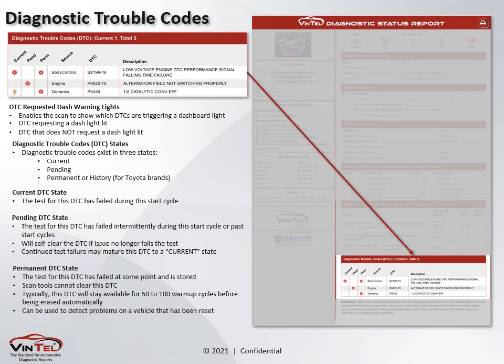So why use the diagnostic trouble codes? It's a great question. You already know in plain English terms simply what parts have to be replaced as well as what the labor is. When you get to this level though, you're typically trying to understand why these DTCs are happening and when they're occurring. So you're looking at states. Is it a current? Is it pending? Is it something I have to worry about maturing as they leave my car lot or as I just bought on the auction? Furthermore, if they say it's been repaired and I don't have any current, I don't have any pending, but I have a permanent code and I have some drive time on it, well, I can pretty much know that that problem was repaired satisfactorily. So it's really diving deep down into the details to understand the mechanical challenges of the vehicle and whether they've been addressed, they're being hidden, or they're still present.